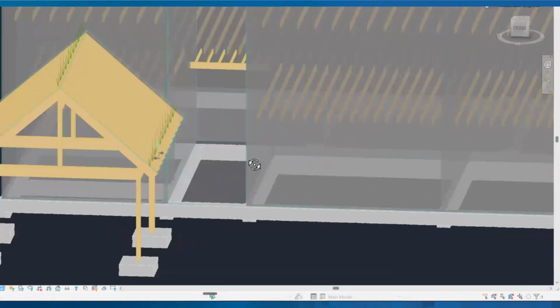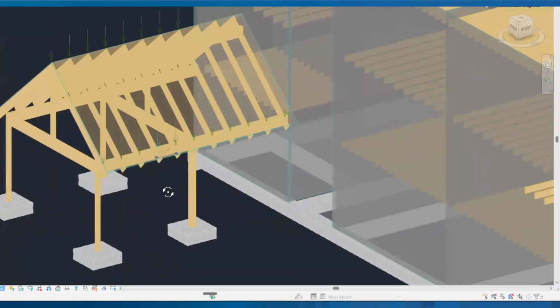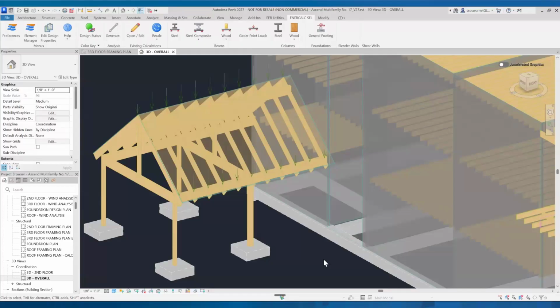What this is doing is generating physical, analytical point loads in the Revit environment at the appropriate locations where those joists intersect the girder. Now that those loads have been generated, I can relaunch the girder calculation for this 2-span girder that projects out of the building, and we can do a design for that girder without having painstakingly designed every element that bears on it. So let's take a look at that. Now that we have girder point loads, we'll relaunch.